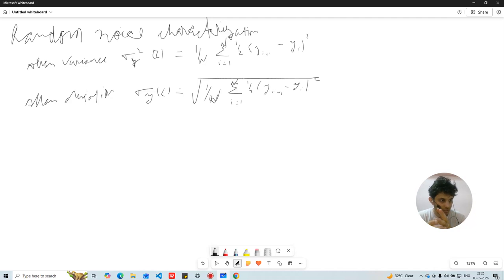Simple analogy. Imagine you walk 10 steps every minute. If you suddenly walk 9, then 11, then 8, then Allan variance measures how much your walking speed changes between steps. What is it good for? It's the most common way to measure time stability for oscillators and GPS clocks.